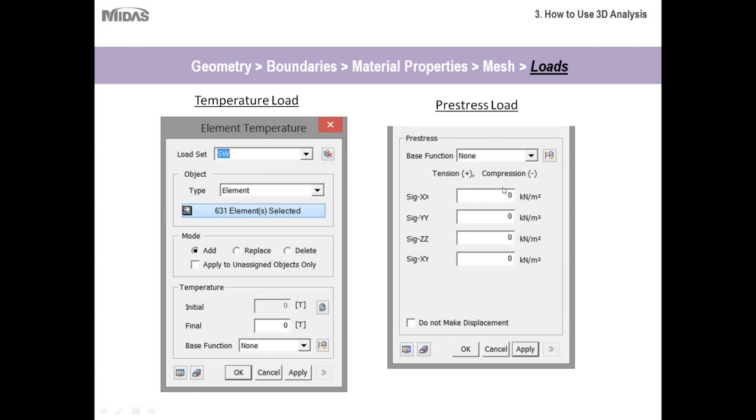You can do all of this just using this option. And the same with a pre-stressed load. For example, if you have a beam or a bridge with pre-stressed tendons, you could simulate that pre-stressed load on those tendons using an option such as this. As I mentioned earlier, we'll go into more detail about these special options later on, but I just wanted to let you know the options that are available to you. This is another unique strength of numerical modeling: you can take more variables into account, and for variables such as this, a numerical modeling approach would really yield good results for you.